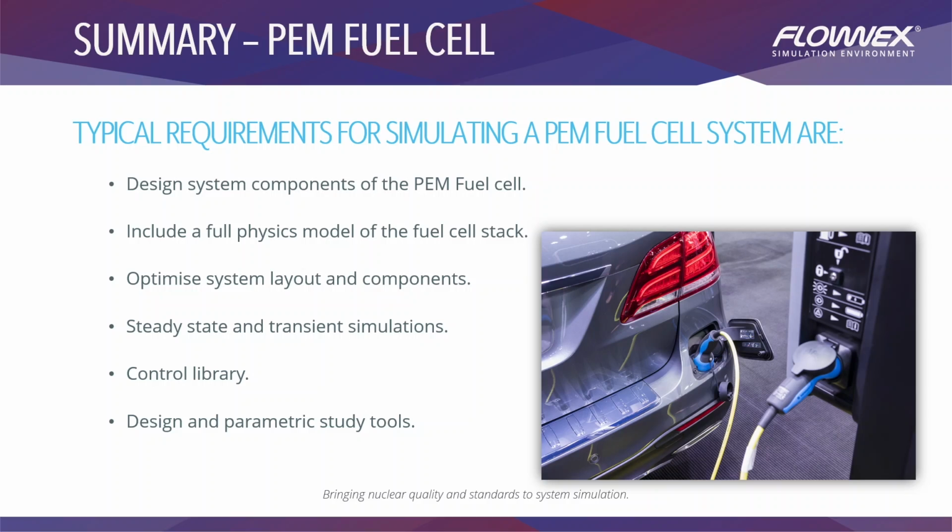For example, different types of cooling strategies can be investigated and compared to find the best performing solution. Instead of using air as a fluid, we can possibly investigate a closed loop thermofluid system using liquid water. We could potentially also investigate different system layouts and understand from a performance and efficiency perspective which one will be better.